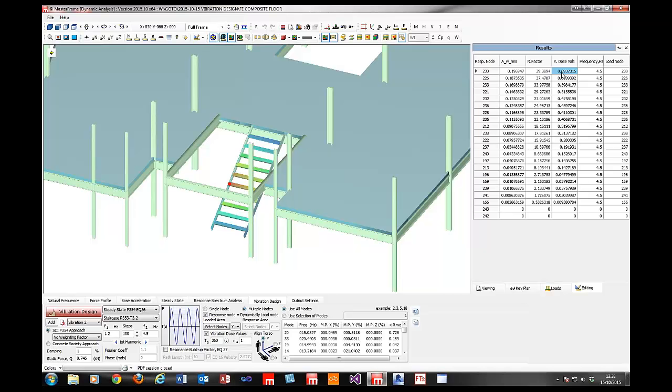Now when we look at table 5.4, it does give us acceptability ranges for buildings, and you get different ranges for day and night. And for a daytime use, you get criteria: one for a low probability of adverse comment between 0.2 and 0.4, then adverse comment possible gives you a range of 0.4 to 1.8, and then adverse comment probable 0.8 to 1.6.